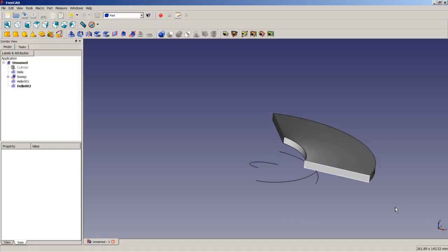So the next thing is that we must duplicate the sweep as well. In FreeCAD, I have noticed that FreeCAD is able to do 2 instances duplication, but not more than 2 instances. It is my personal opinion not to copy too much data to the clipboard, because then maybe you will get into trouble if the data has relations to faces or edges or things like that.